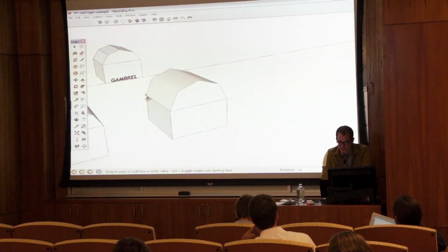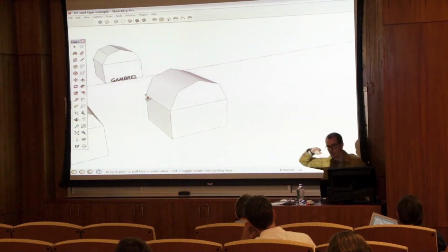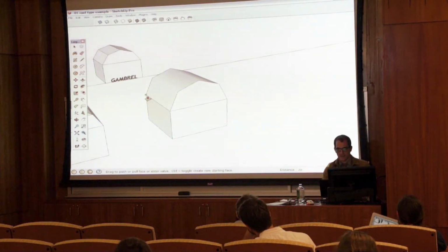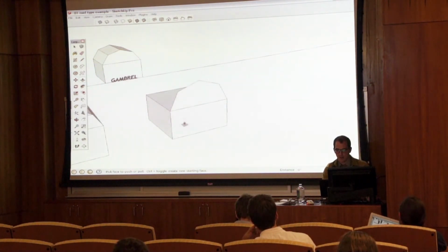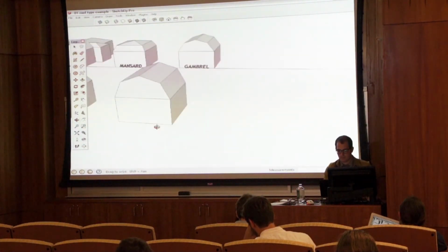Now I noticed some of you tried extruding this, and look what happens when you try to push-pull this. Since the arc is a polyline, it acts the same way that a circle does. It smooths the facets. So see how it's smoothing this edge here and there? To prevent that from happening, before you push-pull this, select the arc and then right-click and explode the curve. Then when you push-pull, you'll be able to push-pull with those segments all separated as individual geometry.